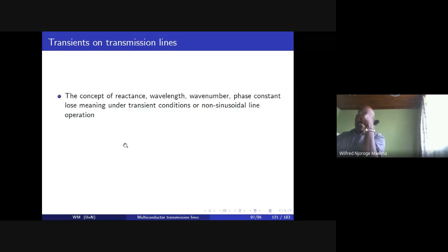So now we come to another concept that is usually very confusing to many students, and this is because many times from circuit theory you've always been dealing with equations of, say for example, if I have an RLC circuit, say a series RLC circuit, I would get that the impedance is going to be given by R plus j omega L plus 1 over j omega C, okay? If it was parallel, of course, it would have the usual expression as well.